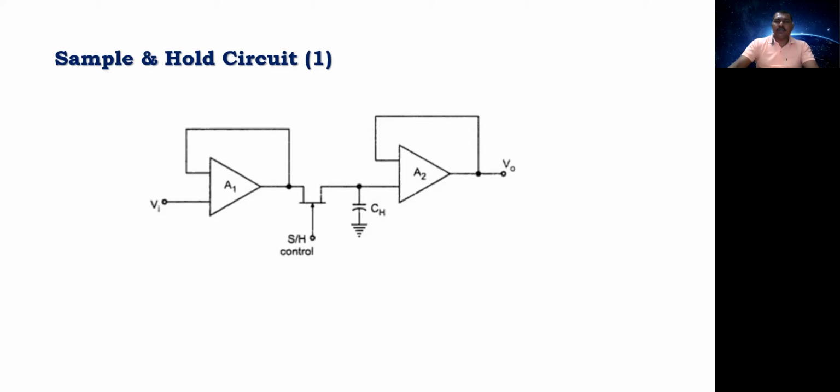So what happens by that time? We store that particular point in this capacitor. During this time, the ADC is going to convert some other point, right? While it converts, we then send this voltage along. So this circuit is called a sample and hold circuit. We are taking samples of the signal and holding them in this capacitor, which is discharged through this operational amplifier.